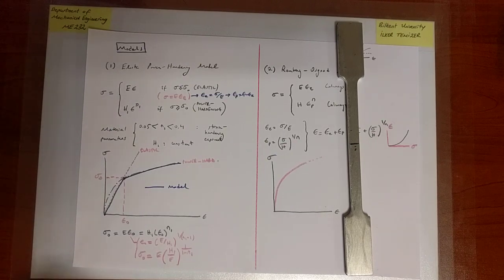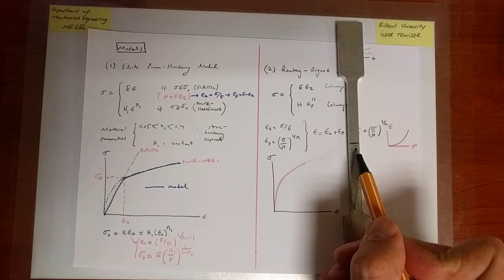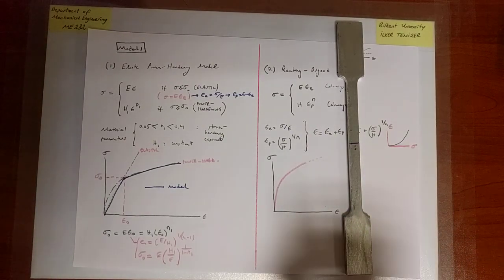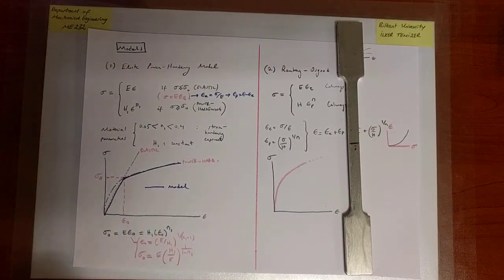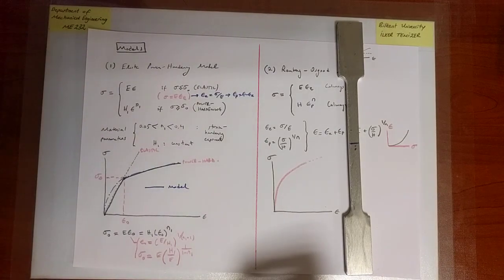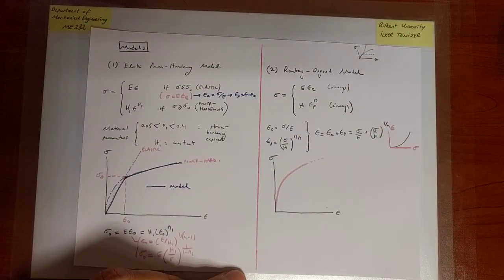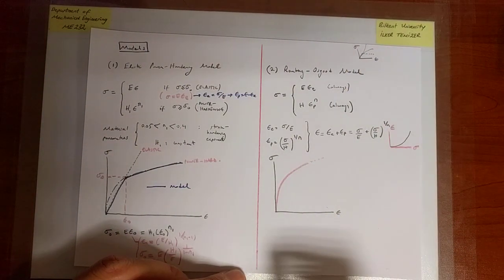And that idea now goes very well hand in hand with our previous discussion of identifying the yield strength when there is no visible corner. We said that the yield strength is the stress when there starts to become appreciable plasticity. This is not appreciable plasticity. It's only occurring in the vicinity of, say, stress concentrations. Appreciable plasticity is defined in our case for these types of stress strain curves through the 0.2% offset method. So in this particular scenario, the yield strength is an outcome of the model.